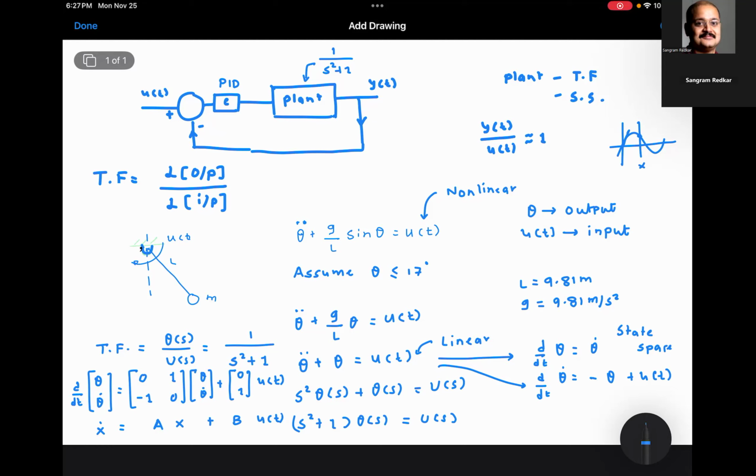So now you have a nonlinear differential equation, and then we will try to find a PID gain that would work with it. But in that step, please understand, your original plant is nonlinear. You are using a linearization, you are using a linear control. So MATLAB would do something called numerical linearization and give you the PID gains. Everyone understood this? I'm going to show you that.